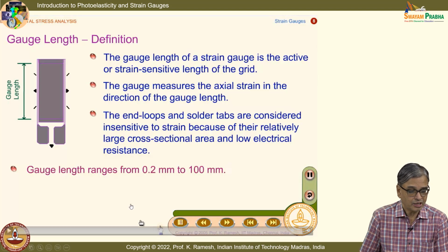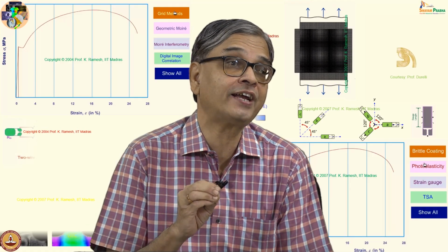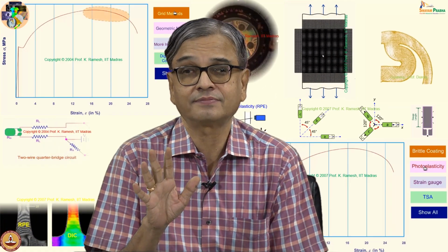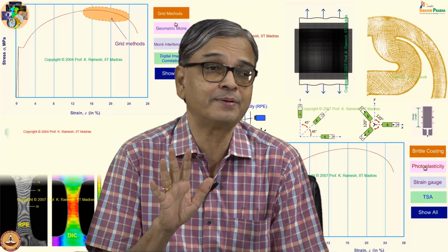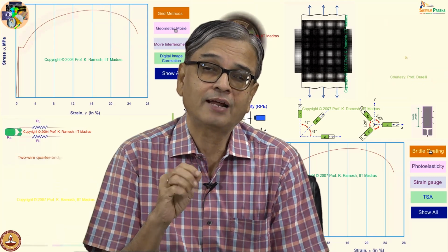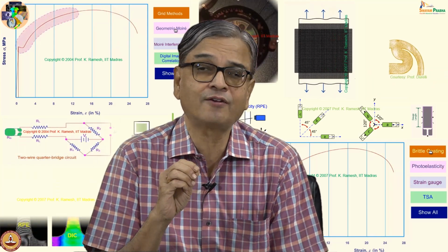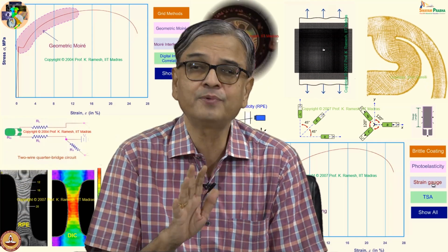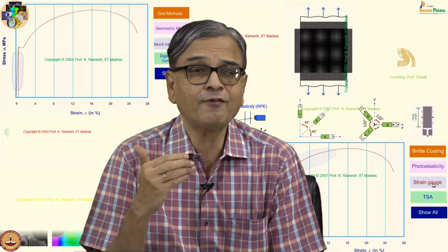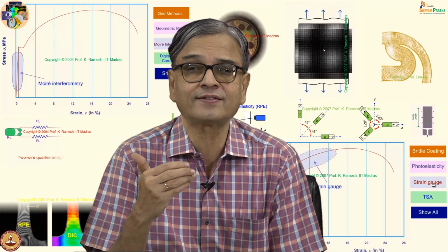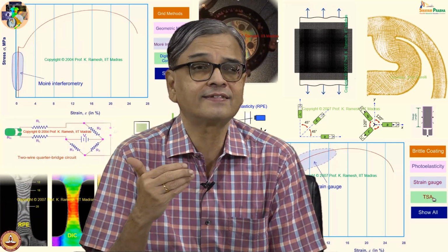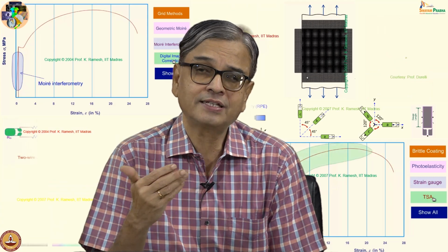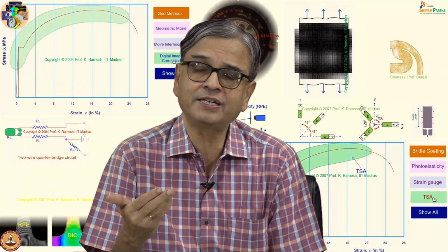So, you have to select what is the gauge length that is appropriate for your given application, and strain gauge selection is also a very important issue. And I want to caution, strain gauge is a widely used and abused technique. People abuse it because they don't have a formal introduction to what a strain gauge is, what are the sensibilities, because the electrical principle is very simple and straightforward.